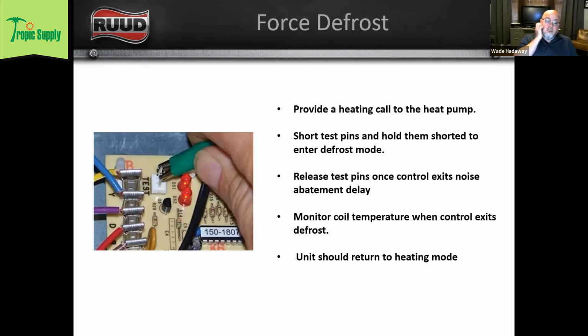The test pins can also be used to force the unit into defrost mode. So you've got to have a call for heating, short the test pins together, and keep them shorted together until it goes into defrost, right? So until after the 30-second sound abatement delay has gone by.